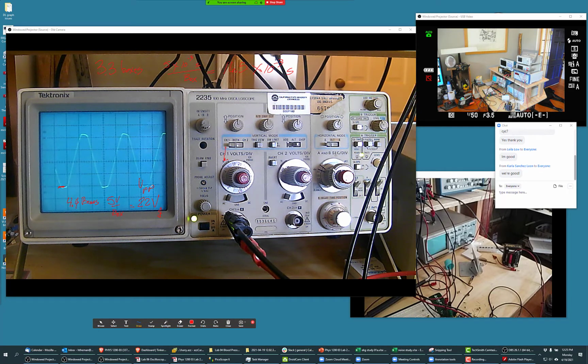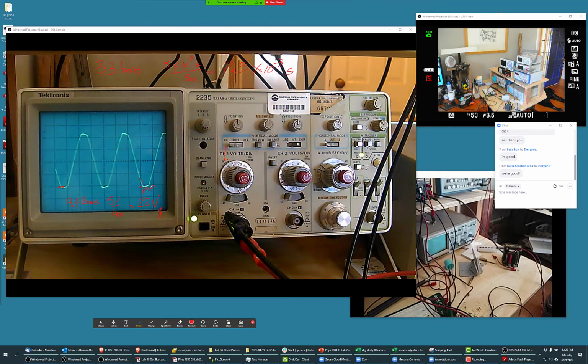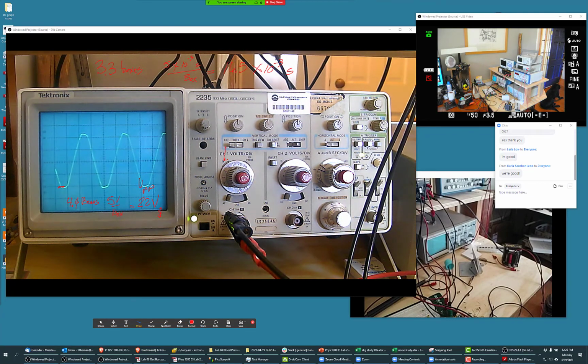Okay. So let's everybody, you know the voltage peak to peak. Everybody please calculate the VRMS. So you have 22 volts peak to peak. Everybody write down what is the RMS voltage then. Calculate the RMS. I'm going to do it in my logbook.